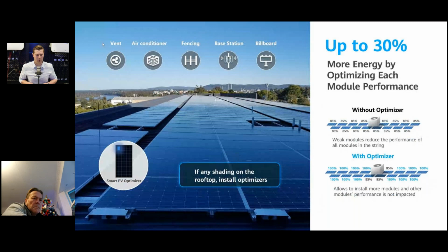And remember one additional thing, that in every commercial and industrial scale inverter, we have 2 PV strings connected to one MPP tracker. So even if one PV module on the string has some problems and we have the current mismatch there, it will mean that the whole MPP tracker will have decreased efficiency. That's why it's important to consider having optimizers when we really need them.